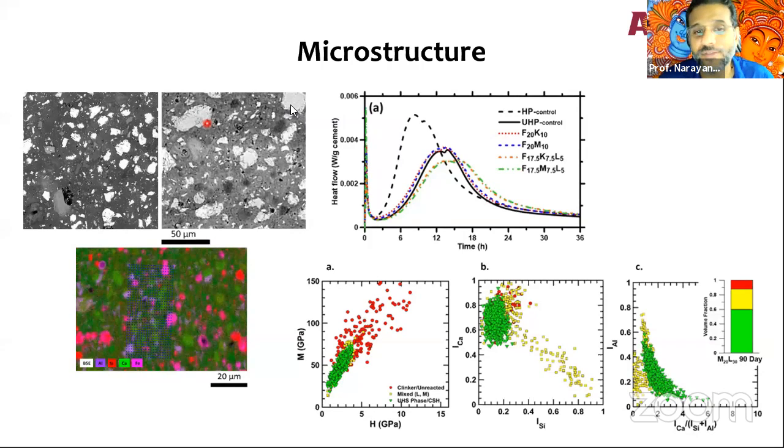That is a trade-off that you will have to live with in this, because if the cements start to hydrate, you can remember your basic cement class. When the cement hydrates, it increases to twice its volume. When the same mass increases to twice its volume, the porosity has to increase, right? Therefore, if the cement hydrates more and more, the hydration products are more porous than the cement itself, which means the structure is going to be less strong.